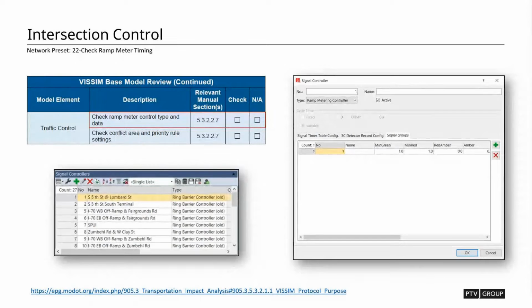There are other types of controllers in the network that you might look at, such as ramp meters. We have some inbuilt ramp meters that have a single phase. So you'll see the controller type is called a ramp meter. It has a single phase ramp meter, so it just cycles based on the flow rate, the desired flow rate that you want on that ramp meter.